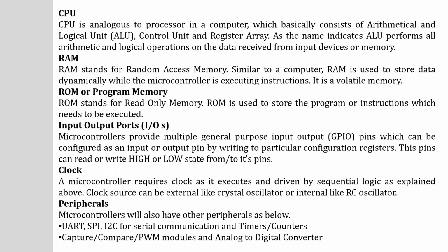Next, ROM is a non-volatile memory. That means it stores data permanently. And next, coming to the input-output ports. The microcontroller provides multiple general-purpose input-output pins, which can be configured as input or output pins by writing to particular configuration registers. These pins can be read or written to high or low states.